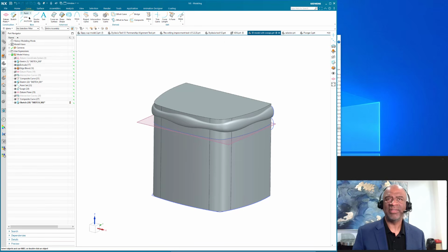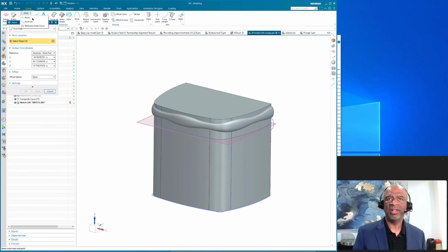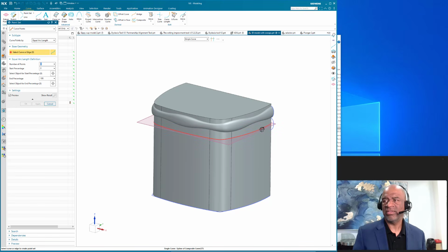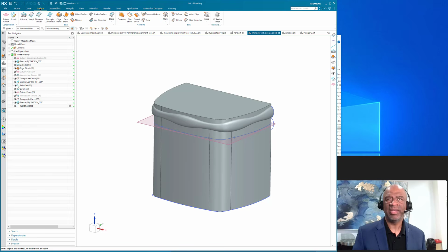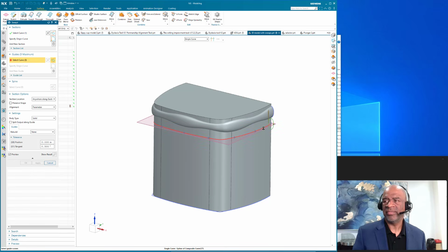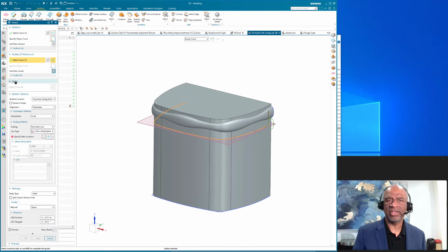Before I do that, I've got to go to the curve function and go to the point set function and select spline. I'm going to put 9 points on it again and say OK. And now I go to surface swept. With surface swept, I select the ellipse as the section. I select the combined curve as the drive curve, and I need to now specify those points again.